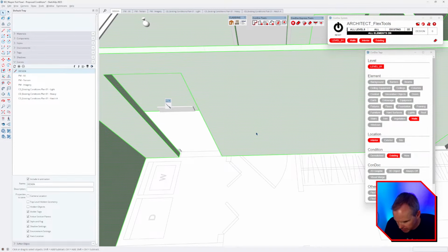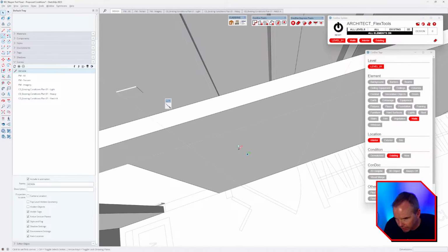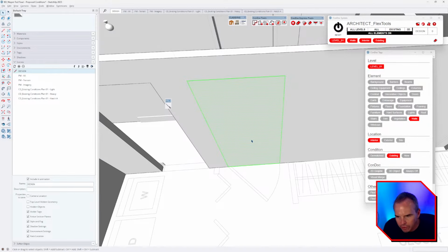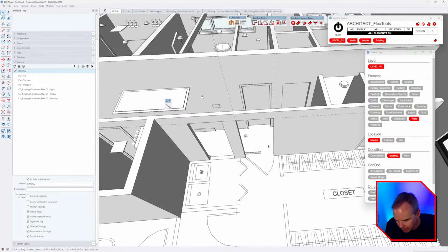All right, so here's what I'm gonna do. It's kind of hard to see those guides when you're in there, but I'll use my rectangle tool, and I'm gonna draw that rectangle, and then I'm going to copy that, and then I'm gonna push pull like that, and then I'm gonna back out of here. I'm gonna paste in place with the push pull tool.